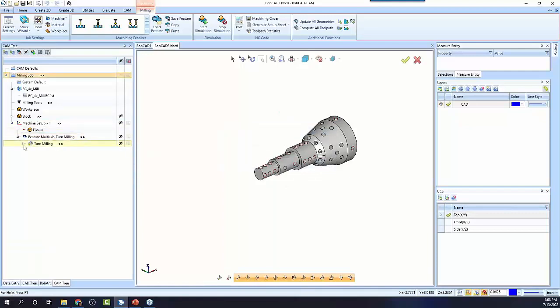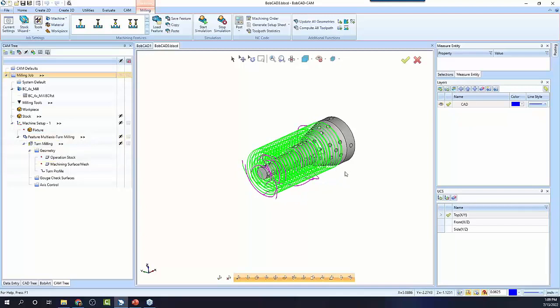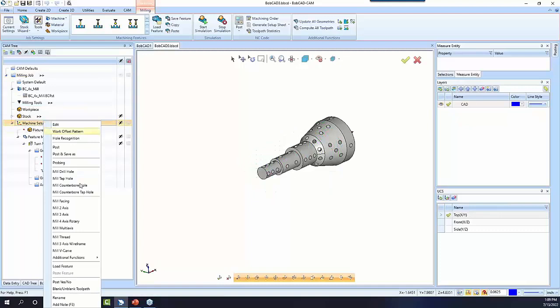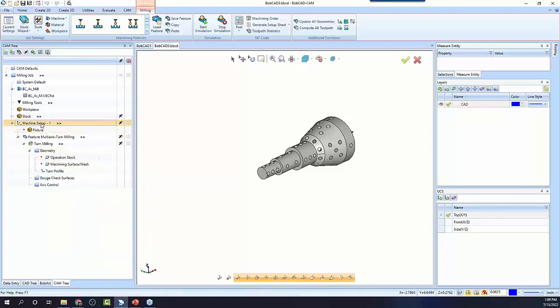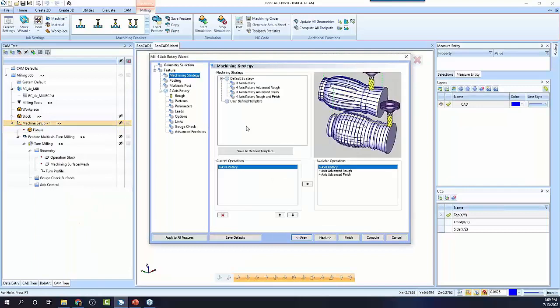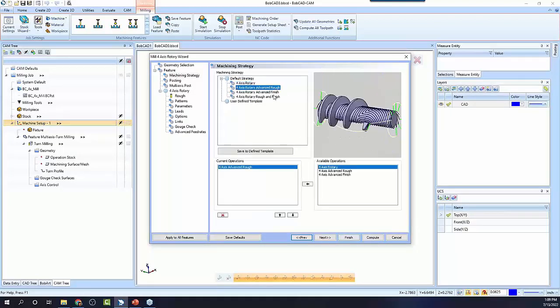This other routine here is a 4-axis Pro toolpath. When we look at 4-axis standard, you get indexing, wrapping, and rotary. If you're in your setup here, you come down, you can add an index system, you can add a wrapping group, and then you also get rotary. Under 4-axis rotary, if you're a Mill Standard user, you would get this 4-axis rotary. If you're a Mill Pro user, that unlocks these additional advanced rotary toolpaths.